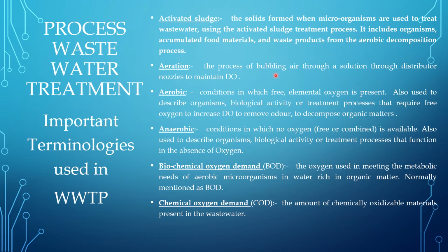Aeration: the process of bubbling air through a solution through distribution nozzles to maintain the dissolved oxygen is called aeration. Aerobic conditions: a condition in which free elemental oxygen is present, also used to describe organisms, biological activity or treatment processes that require free oxygen to increase DO, to remove odor and to decompose organic matter. Normally the aerobic processes are preferred, in which the aeration is given in the aeration tank, which increases DO. We have to maintain DO around 2 to 5, which will help to decompose the organic matter as well as